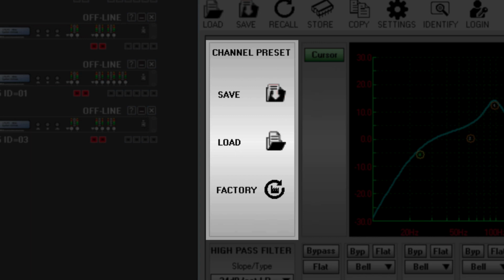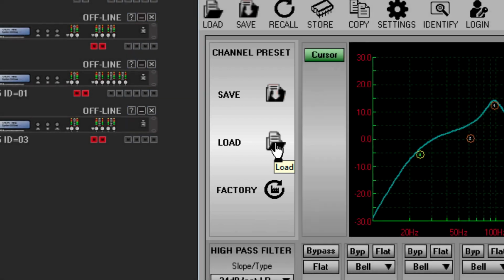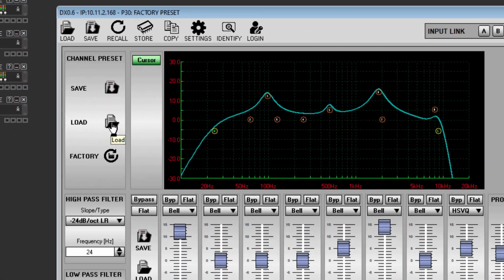The output presets contain all the output parameters, crossover filters, box equalization, gain, delay, and importantly limiters, so that any connected Marin Audio speaker will sound exactly as intended. The output presets are locked, so as long as the correct preset for any given speaker is selected, it isn't possible to change the EQ or just limiter thresholds, so the sound quality and protection for the speaker is always maintained.